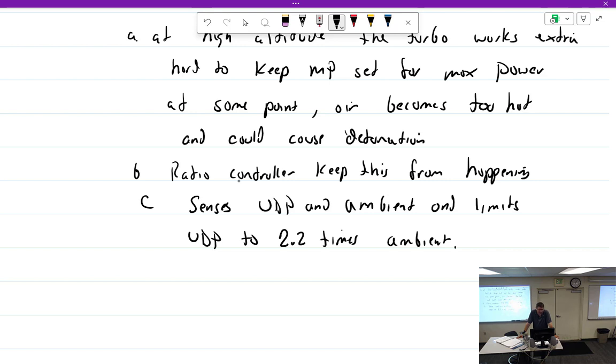So, okay, engine's off. Wastegate is in the turbo off position. We start up the engine. Oil pressure is going to go to the wastegate, flow out the wastegate to the controller. What are both controllers probably going to be saying at that point? We need more power. Yeah, we got nothing here, pal. So they're going to close off. Definitely the absolute is going to close off.